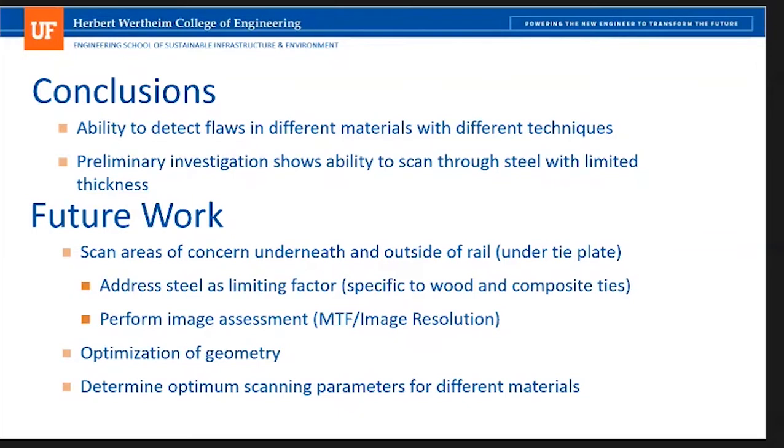We utilize a number of image assessment techniques, which are in the works right now. Some of that is being performed, and some of that work with the probability of detection model that I was talking about. And then when we move through this, we're going to be really optimizing our geometry, both of our X-ray source and our detector, and getting optimum scanning parameters, kind of our tube settings for different materials.